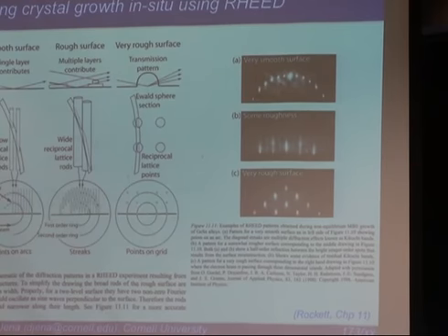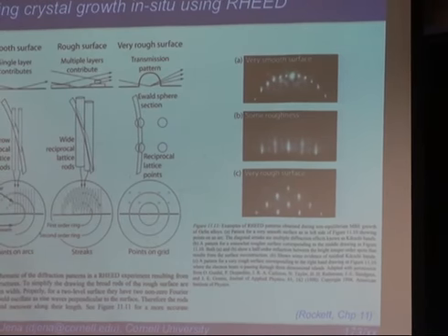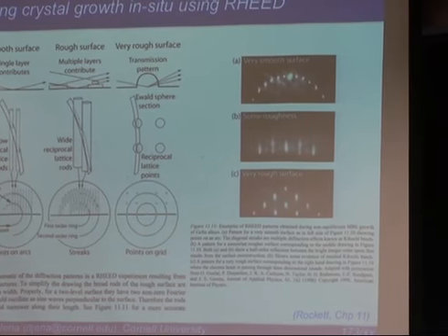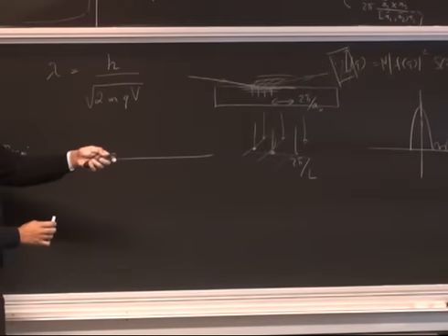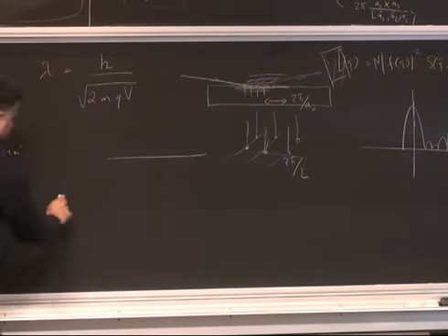It's not really polycrystalline, but because now the electron beam has to transmit, not just reflect, but also transmit through these. So if your surface was like that, you'd get very sharp spots, and you will also see some of these extra lines called Kikuchi lines. We can describe that later.